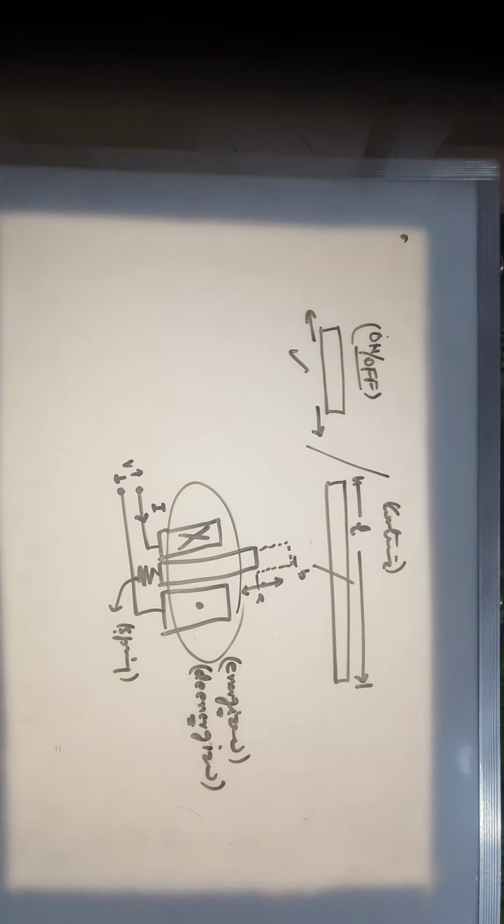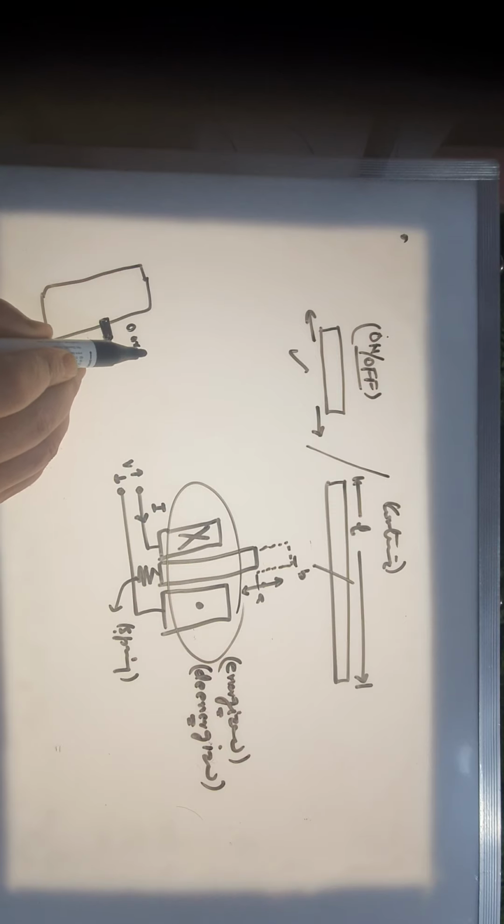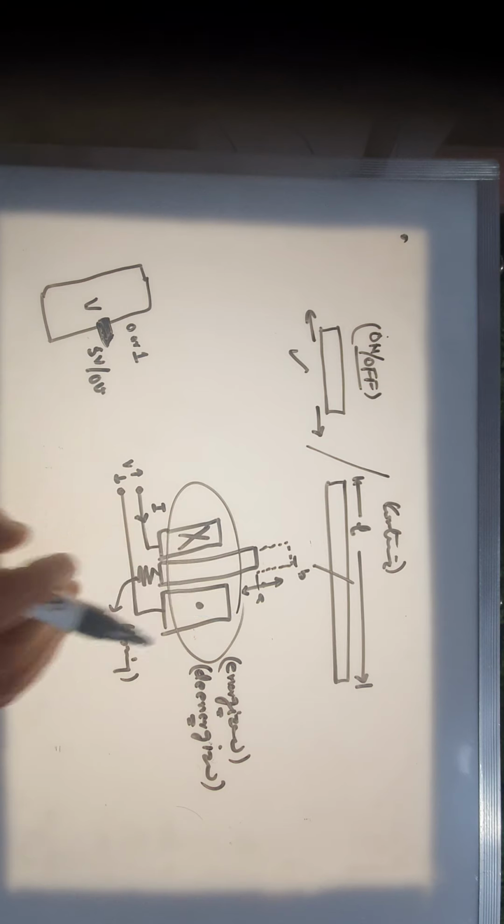So in order to get this solenoid operated by a controller, on this side we have a controller. That controller will be simply providing us the output in the form of 0 or 1. That is the logical side. Or if we take the voltage variable into consideration, depending on the type of processors, it can be 5 volts or 0 volts. So if you provide it with this logic one, that is 5 volts, it should be able to go up, and if you provide it with 0 volt, it should come down.